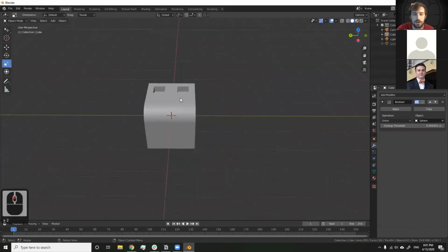Maybe you start off with a default cube and make that into a body shape, and then you make an arm out of a sphere over to the side. Then you can Boolean union it onto your body, and now you have just one file again without having to worry about how you got your geometry going from a cube out to a sphere. So that's the Boolean modifier.